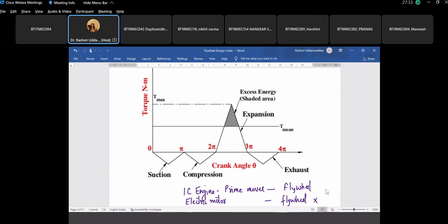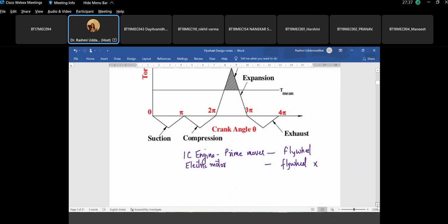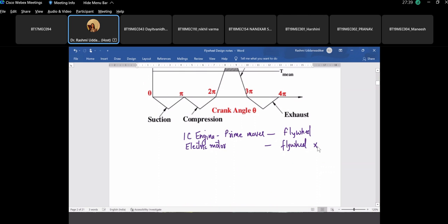Now, the application might be one where the load is continuously varying. So, if the application requires variation in torque, then the input machine component which is supplying power uniformly, this is not continuously consumed, and hence there is a variation which needs to be stored in the flywheel.